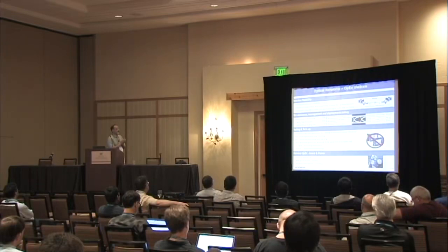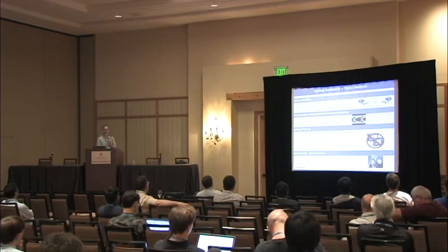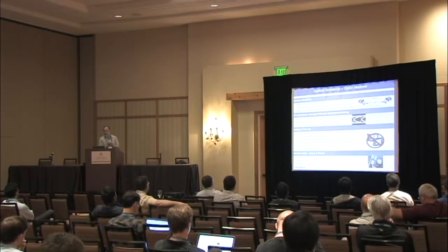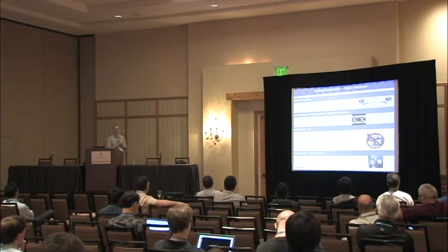It's important to have insurance, and that's basically the SLA assurance management and deployments, debugging tools. If everything goes well, you don't need those. If anything goes wrong, you should be able to look at the performance monitoring and see where the packets or your traffic is disappearing. You should be able to look at the optical signal quality, to look at the transmit level, receive level, like we showed here, and to understand why your optical design doesn't work. You should be able to look at, and that's the digital diagnostic, the eye-grade mask. That's a famous picture that shows the quality of the signal. It should be an open eye.